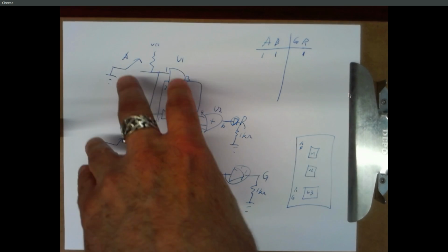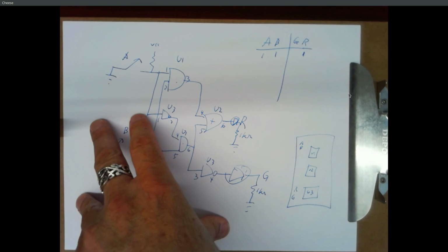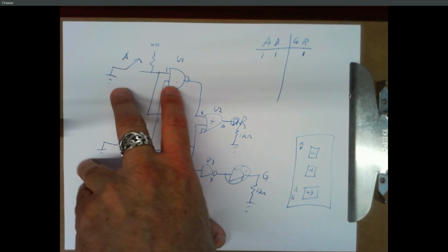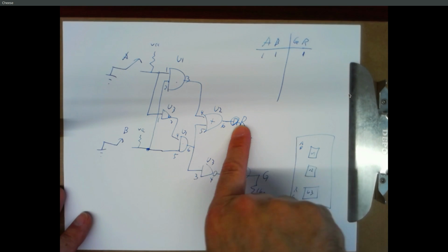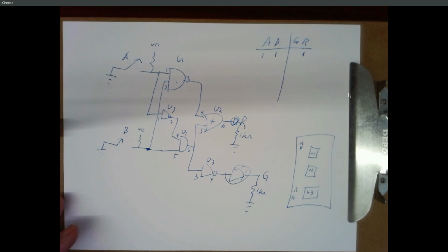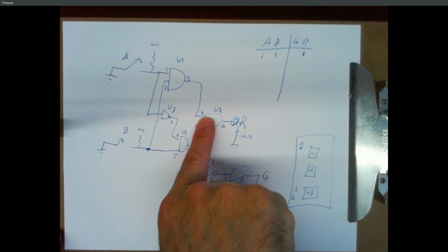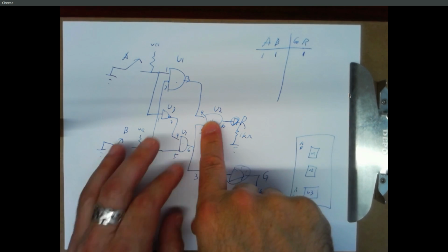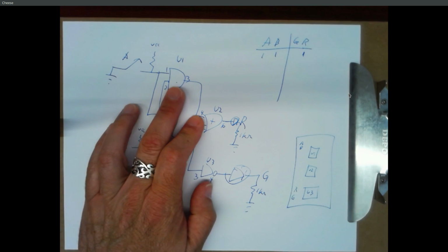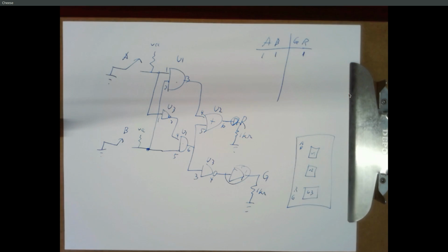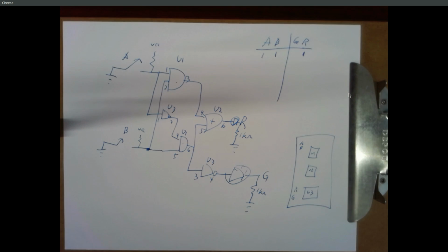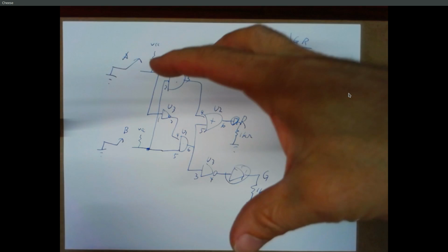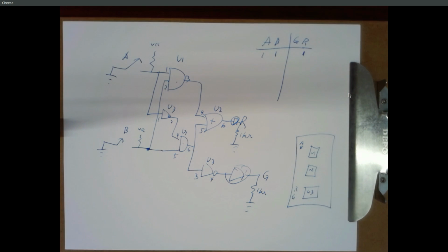This is why Izad and I are always telling people you got to do the wiring diagram first. Because if you have this, this is how you can start here, work your way back. And eventually you're going to find something where, you know, this is outputting a 1, this is outputting a 0. Okay, there's my problem. I connected this to pin 3 on the wrong chip. All right. And it's very methodical to find a problem with a circuit at that point. Other than the fact that you've got 100 wires you have to work through.